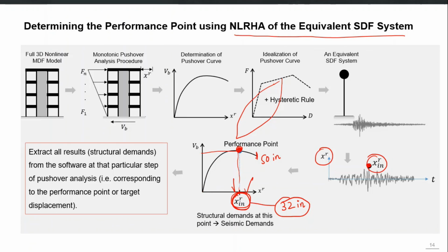But it is generally recommended to go beyond that to see what will happen if the peak inelastic roof displacement is exceeded in a future earthquake, right? So it is always recommended to get a full picture first and then estimate the peak inelastic roof displacement.